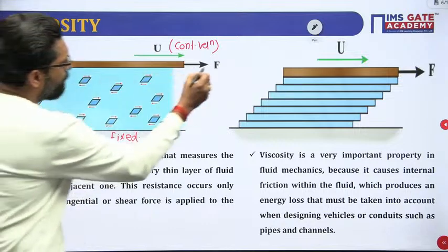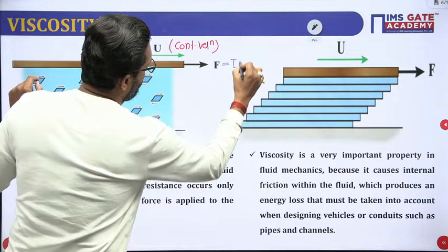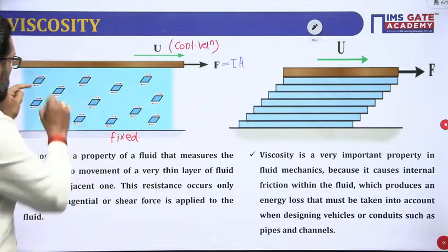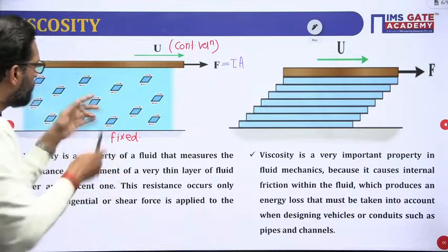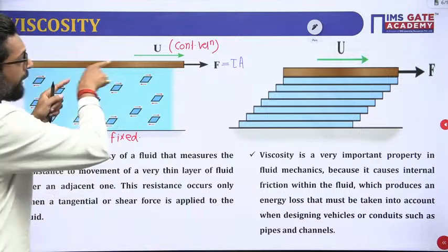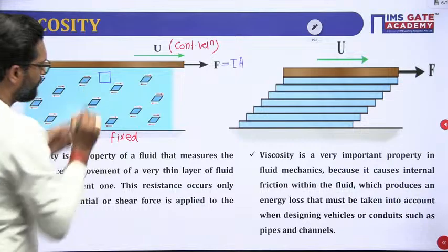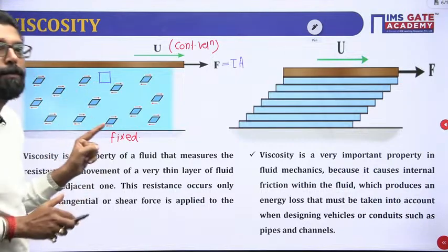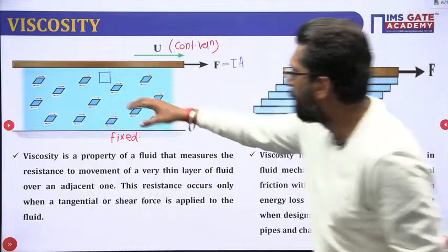Because there must be a force, and this force is equal to stress times area. So there must be stresses there. We'll discuss this thing. If you select a chunk, an element of the fluid, the points try to deform. In this case, you never draw the fluid undeformed. This is wrong. You should always draw the fluid in a deformed position.